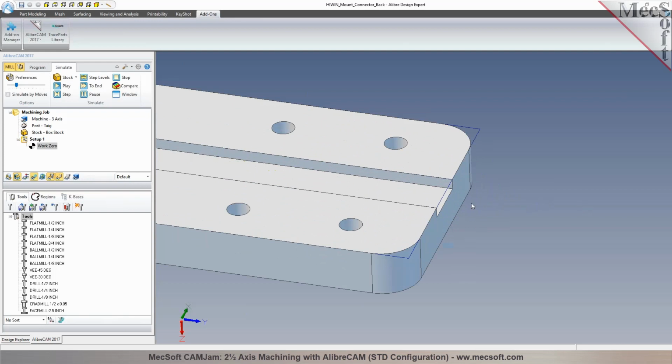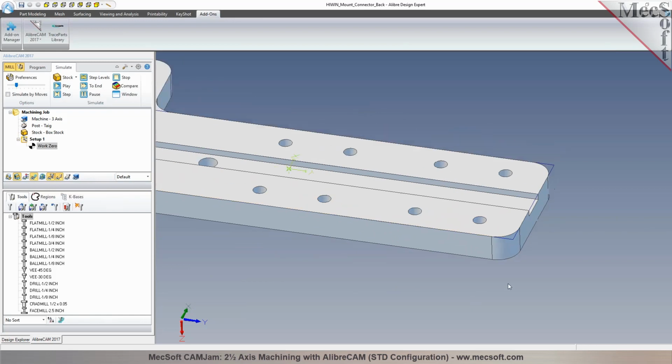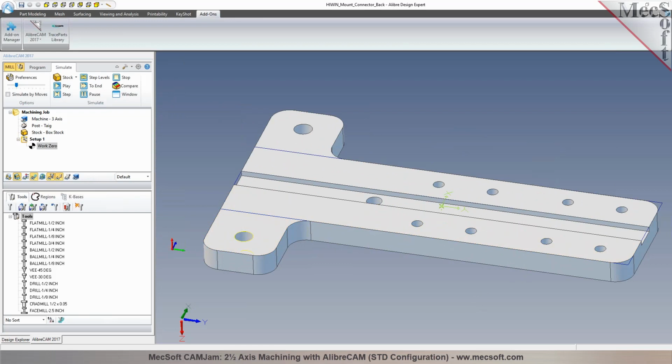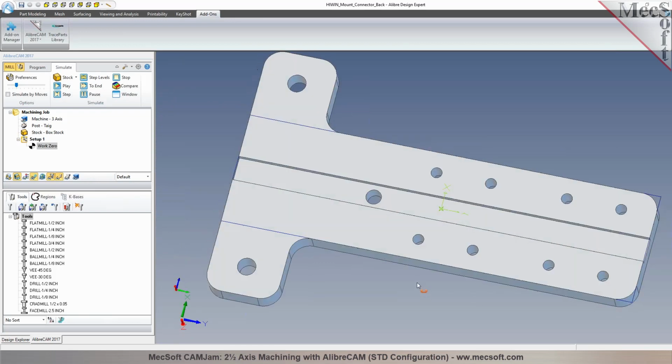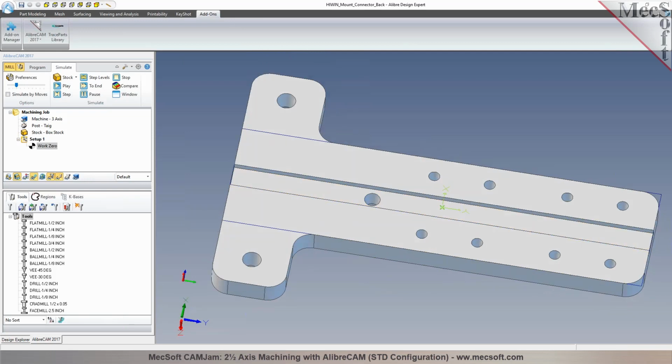Okay. All right. So now I'm taking some measurements in here. So this is about 0.276. So you could probably use a 1/4 inch end mill to cut that. And let's look at the diameter of the hole. It's a 118 diameter. Okay. And then this one over here is a 197. So we have holes of different sizes in here, right? Yeah. You have 165 diameter.